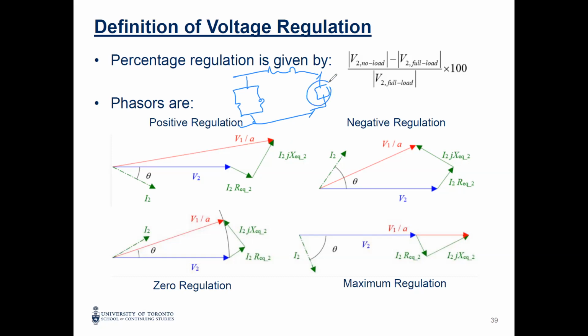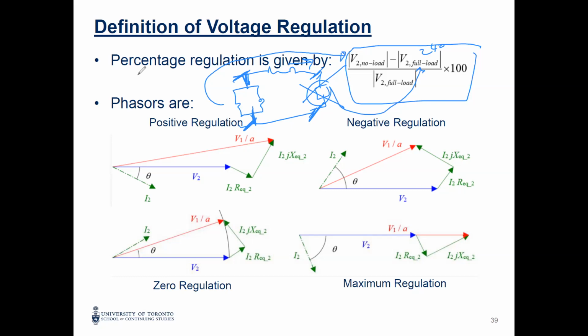With the load, it's the full load voltage, the 240. Without the load, this is what we calculate, because no current will flow here. It will be the voltage no load. So the voltage no load relative to the voltage full load as a percentage, this is what we call the voltage regulation. If the voltage regulation is high, that is something bad because it means there is a big difference between having the load and not having the load. If it's smaller, then it's good enough.